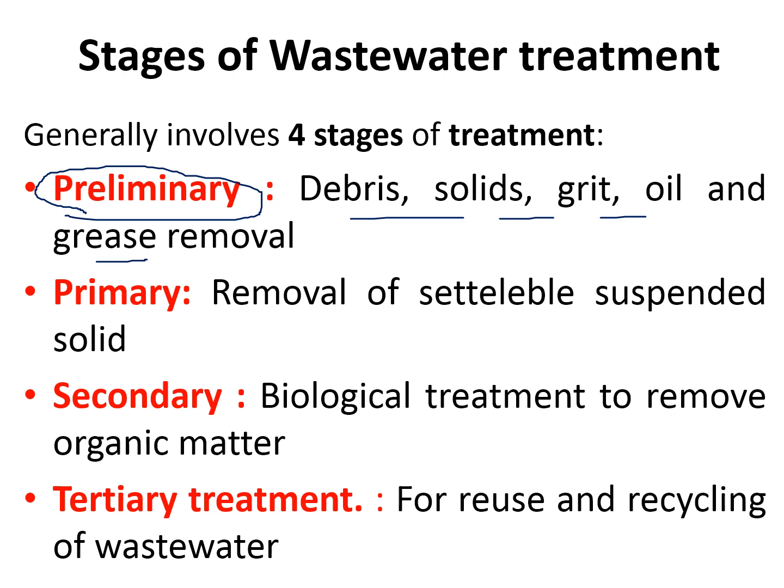So these are all to be removed in the preliminary treatment method. Next is primary treatment. Here our main aim is to remove the settleable suspended solids. So all which can be settled down under the force of gravity, generally that are to be removed within the primary treatment.